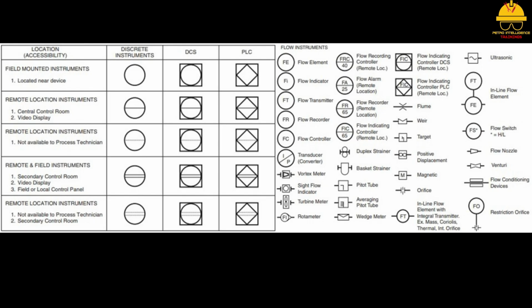Many flow elements work directly with transmitters. These flow transmitters are designed to send a signal to a controller. An example of this is a differential pressure transmitter that is working with an orifice plate. The transmitter is typically mounted below the line to keep the legs liquid full.